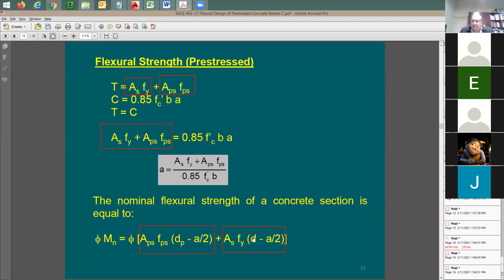Is that typically waiting the, was it 60 or 90 days or whatever it is for concrete to reach the maximum amount of compressive strength? Usually it's going to be 28 days, but there are additives, like admixtures, that you can add to concrete so that it can gain the full strength in 14 days or a week. Oh, okay. Yeah.